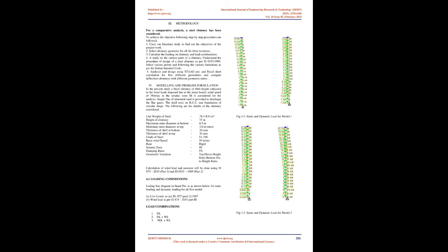The objective of the current study also covers the aspects influencing tall chimney design. Loads are calculated as per code IS 4998, Part 1, 1992. The analysis is done using STAAD.Pro. The deflections are determined and checked whether they are below the limiting value as mentioned in the code.